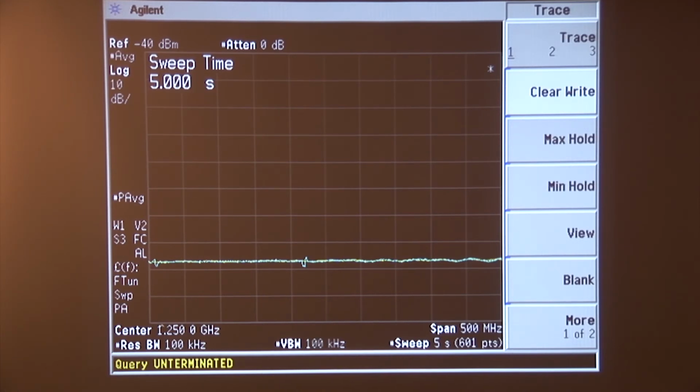Is on. Oh, amplifier is not on. That would explain it. There we go. Okay, amplifier on. Now, remember, this is the noise floor of our measurement system. I actually had 10 dB of attenuation in before that I've removed, so we're eating up 10, 20, 30 dB of dynamic range needlessly. So let's go ahead and put in 10 dB, and in fact I will demonstrate it like this.